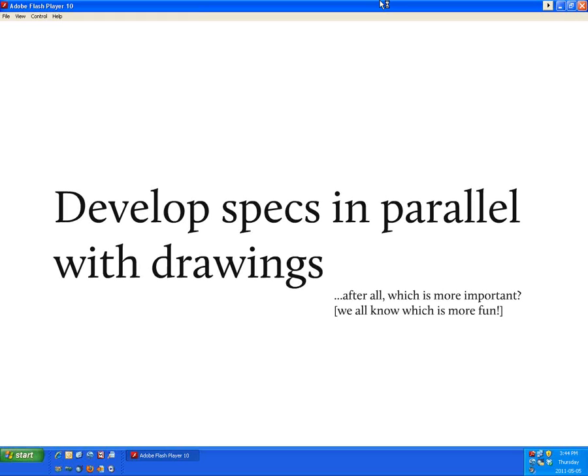On a more serious note, though, John Horner makes a good point. He says, unless a drawing term is exactly the same as used in the specs, it is not the same thing. For example, "metal roofing" on the drawings is not the product "pre-finished metal roofing" in the specs, regardless of intent.